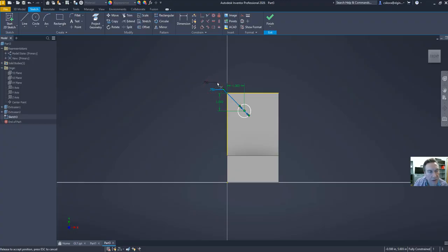Let's get it up there. Okay, and you want to have your dimensions located close in proximity, but not overlapping each other, so you're not reading way off to the left-hand side what the dimension is, unless you have no other option.